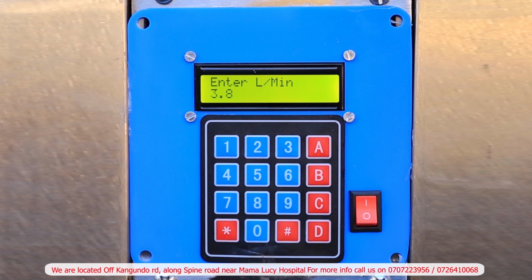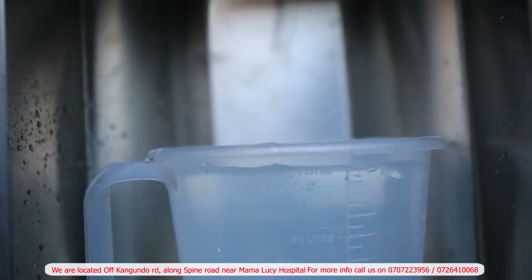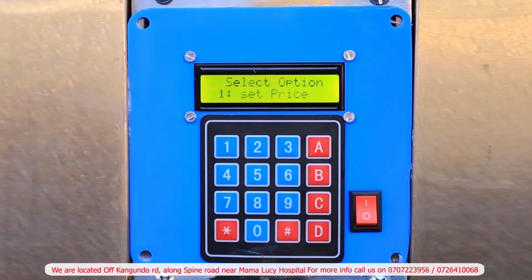If the dispensed volume does not correspond to the keyed in quantities, you go back to the calibration function and increase the value you had input. We had put 3.8, therefore you can put 3.9 or 4.0 and keep going back to check if the values correspond or match. The other function is viewing and clearing of your sales.